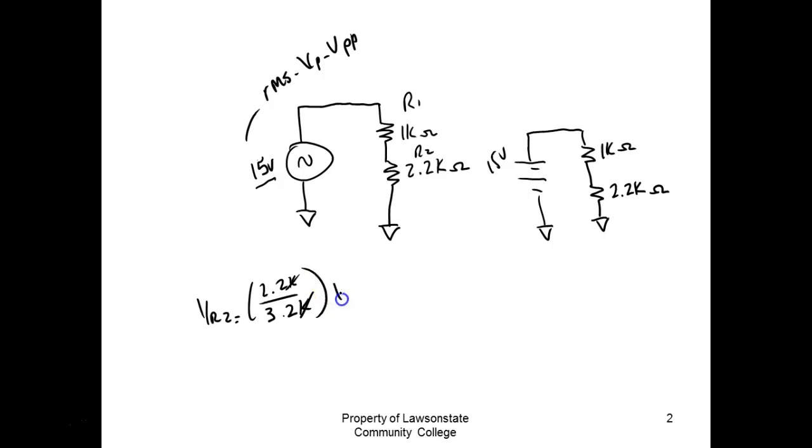Then I can come up here and multiply this by the applied voltage, no matter what the applied voltage is, right? You understand? So how much voltage would VR2 drop? 2.2 divided by 3.2 times 15. 10.3. So it's going to drop about 10.3 volts. But notice, I say, okay, how much would it drop if I raised the voltage to 60 volts? You'd say 2.2 divided by 3.2 times what? Yeah, times 60. That's what's nice about the voltage divider formula.